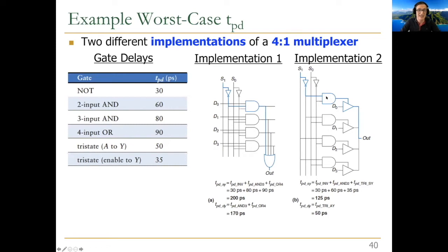Essentially, AND gates are used to drive the select signals or enable signals of the tri-state buffers, as we discussed. Somebody asked, wouldn't we have to consider wire delay? Absolutely. You need to consider the wire delay also. In all this I'm doing, the assumption is that wire delay is 0. But in real life, you may need to consider it, certainly. So that's a very good question. We're going to ignore the wire delays in this lecture, but the issue is actually more complicated, as you mentioned.